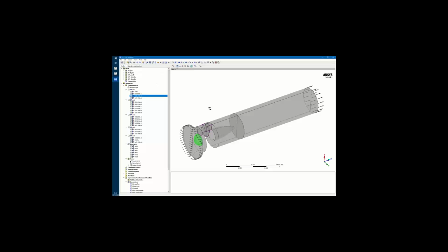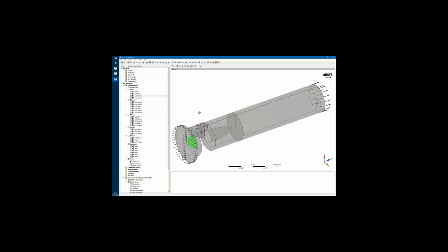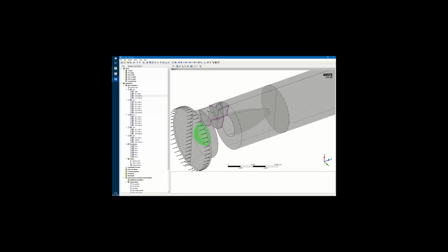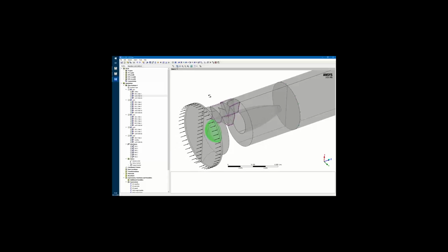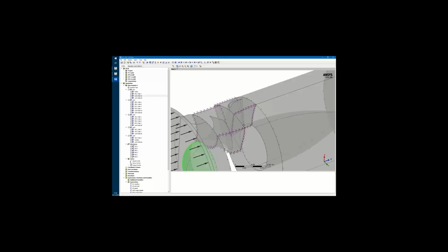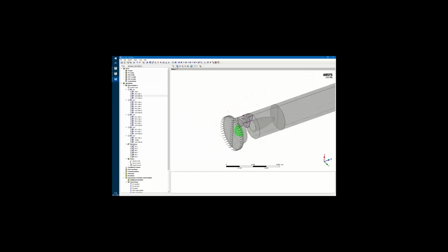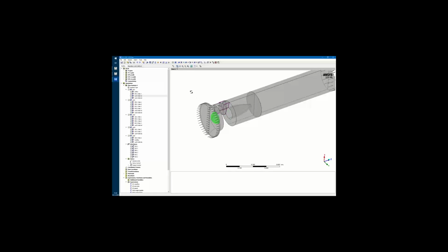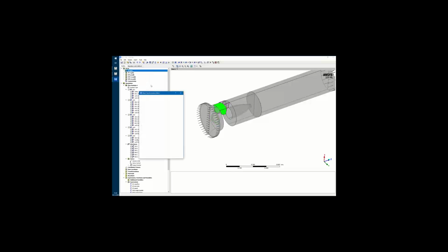As you can see in the model, I have modeled all components as a 360-degree model, except for the plate passages, which have been modeled inside of TurboGrid. Of course, inside of CFX-Pre, you have the option to quickly modify your setup and make a 360-degree model from your plate passages. This can be done really easily by choosing the transform mesh option.